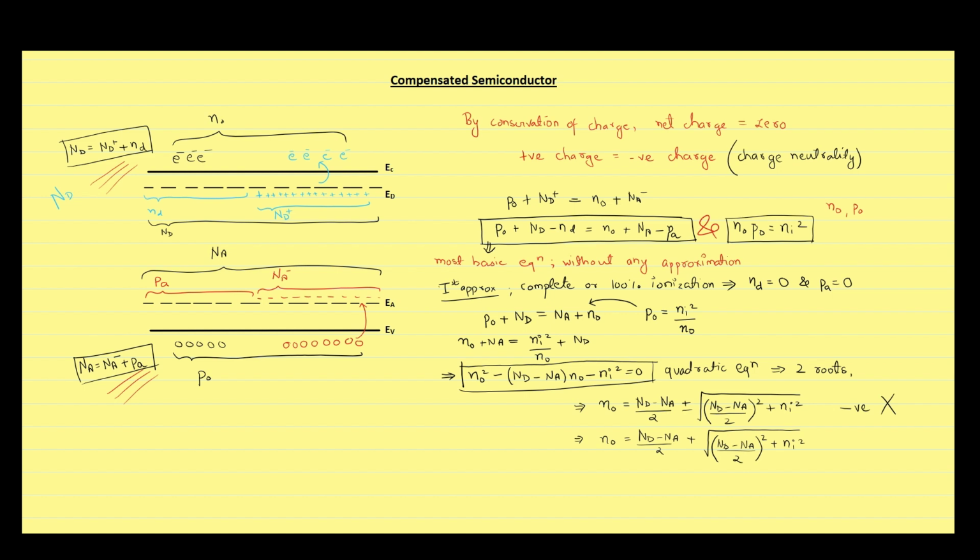For getting this value, we have assumed one approximation, that is, the complete annihilation has taken place, and the other, which is an important condition, is that the semiconductor is non-degenerate type, meaning the doping concentration and acceptor concentration are significantly greater than intrinsic concentration as well as fairly smaller than effective density of states Nc and Nv.